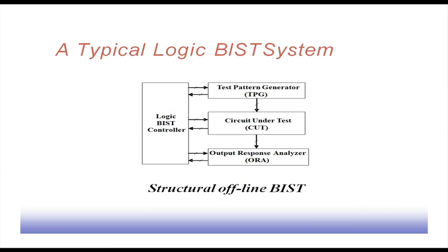In case of BIST, we do not have any other ATE, but there is a test pattern generator which is integrated with the circuit, and there is an output response analyzer which is also integrated with the circuit. In the deterministic case, this TPG and ORA were part of the ATE. Now, I do not have this TPG and ORA separate, but they are part of the circuit itself. The advantage is that from the outside world you just need to tell the system to start testing. There is no further requirement of transferring test patterns to the circuit or getting the responses and analyzing them.